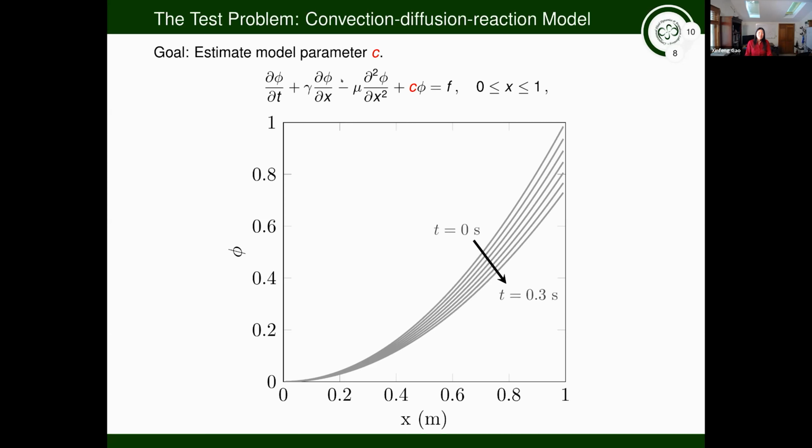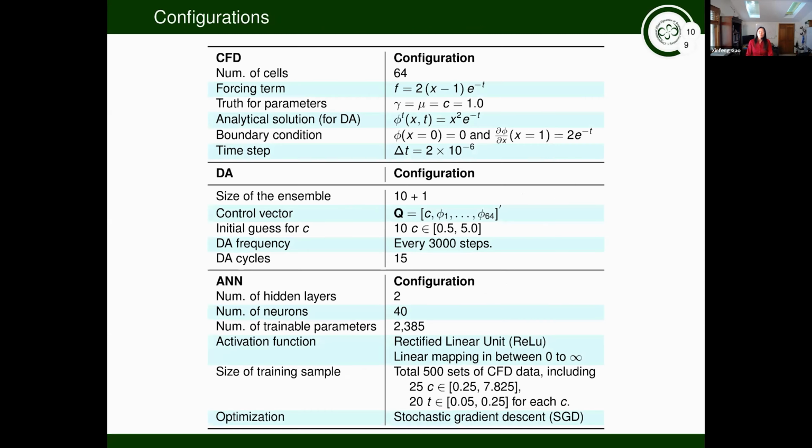And this is a nice model, simple, yet it still shows three physical processes as in many fluid dynamics problems. You have convection, you have diffusion, and a source. And this figure simply shows the solution's spatial distribution over time. So from time 0 to infinite time, eventually the solution will be 0 in the domain. So we know the analytical solution.